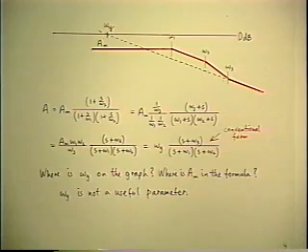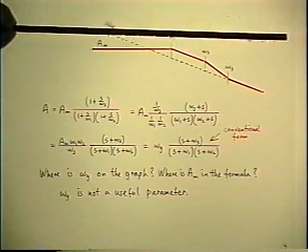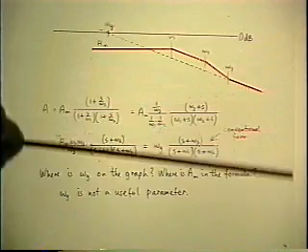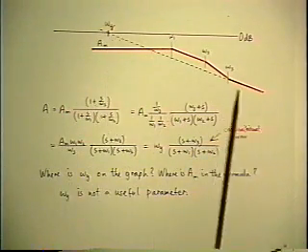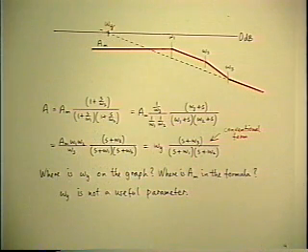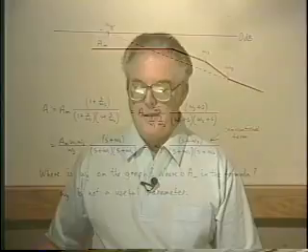So there's one possibility. And again, I don't know where to draw that line without knowing numbers. It may be at any vertical position, but wherever it is, omega y is the frequency where that final asymptote crosses 0 dB. So it's the same result as before, except at the other end of the frequency scale, and the same conclusions apply. This conventional result is correct, but why obscure the important quantity, which again is AM? Why obscure that in favor of some other quantity which you don't even care about?